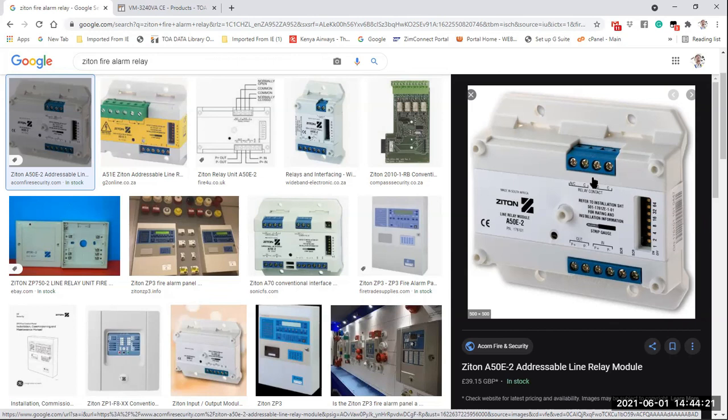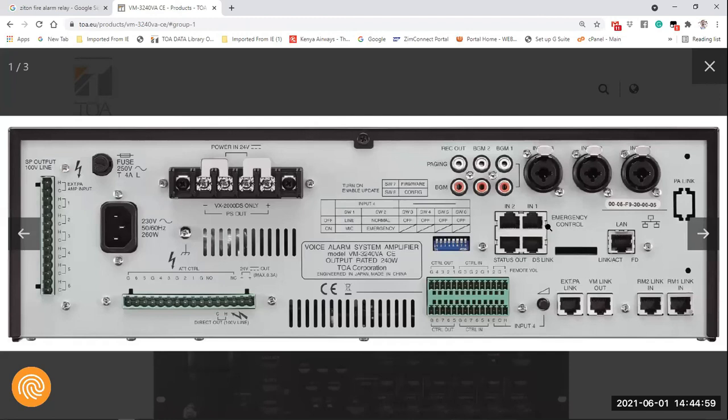So physically on site, you need to have 2 relays. It might be different model of relays, but you must have minimum 2 relays. So these 2 relays, if they ask you, tell them I want a normally open relay times 2, 1 for alert on single knock, 2 for evac on double knock. That's the point. So you must have minimum 2 relays like this, which means if you have relay number 1, you then connect your orange, white pair. This relay is done. Relay number 2, you then connect your green, white pair, which is now what is coming from here.